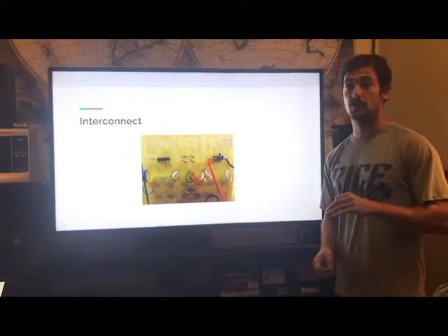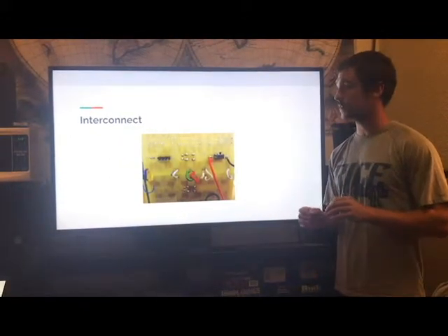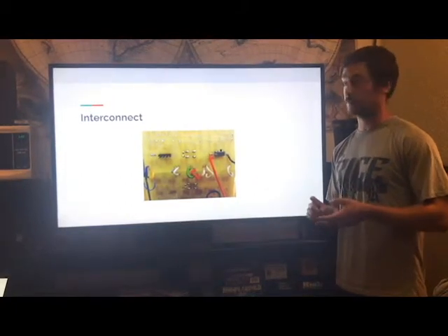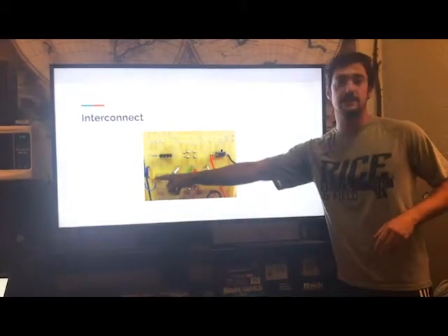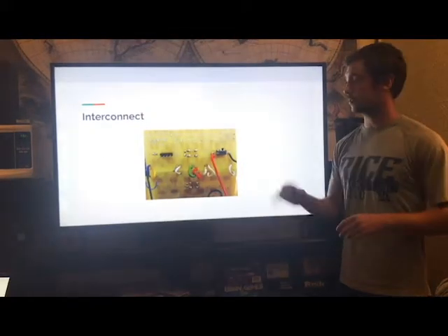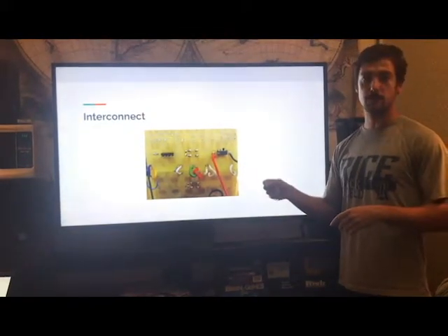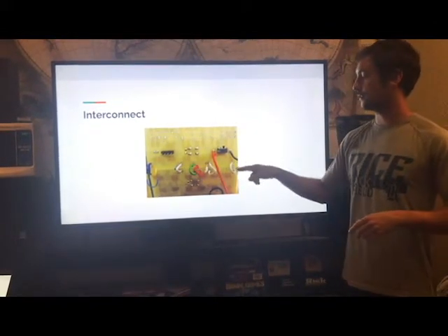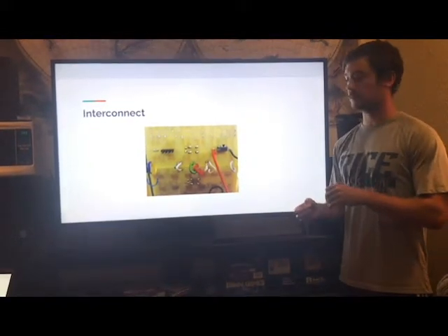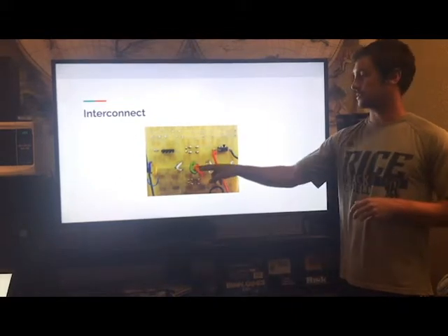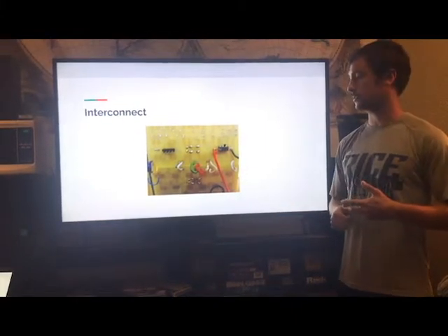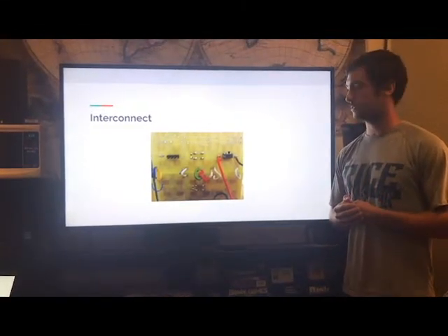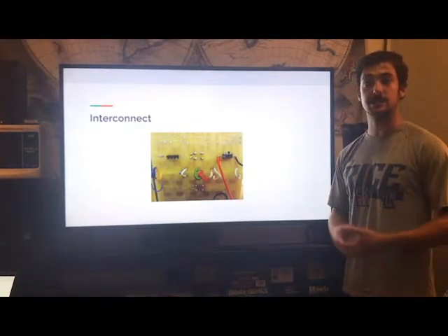Because we were so thoughtful with how we prepared our PCBs, the interconnect between faces was very comprehensible and very clean. Seen here is the data and clock interface across faces: data in and data out, clock in, clock out. And these 5 wires show the connect between buttons, and these 2 wires are for power and ground, totaling a total of 9 wires between faces and allowing for something clean and very easy to debug when necessary.